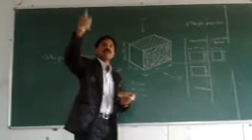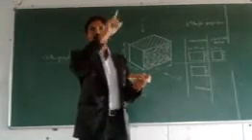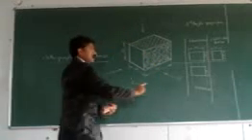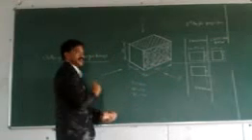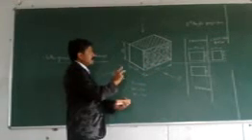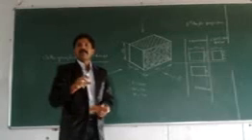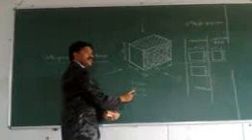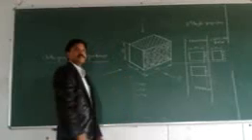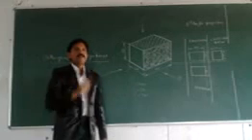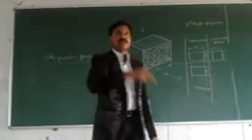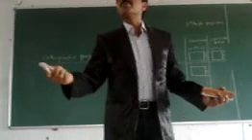That means you have to observe from the top direction. That is the direction at the top. It is not enough to select the front view. So obviously it is either this direction or this direction. Here, when this confusion takes place, simply compare the dimensions. The length is 100 and the width is 50, and 40 is there. Simply compare these two dimensions, 100 and 50. Which is the larger one? 100 is the larger one. So obviously we select the front view from that direction only.